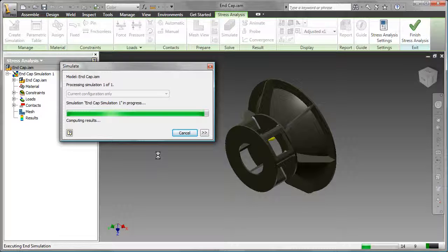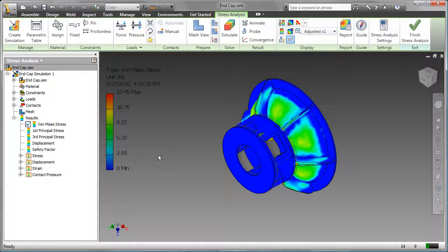You can calculate a factor of safety as the ratio of the maximum allowable stress to the maximum stress the part will ever experience. In this design, we're using yield strength as the maximum allowable stress because we need to avoid any permanent deformations. The yield strength for this type of steel is 40 ksi. So to get a safety factor of 1.5, we can never exceed a von Mises stress value of 27 ksi. We also want to make sure the displacements aren't more than 0.02 inches. For each simulation, we'll be checking against these values.